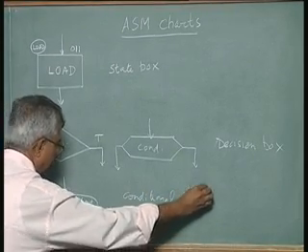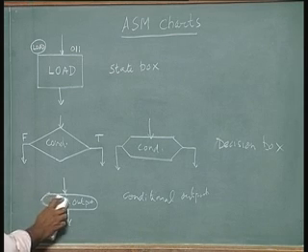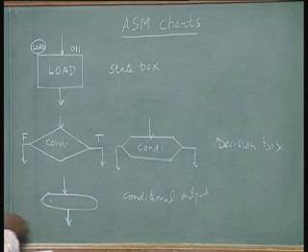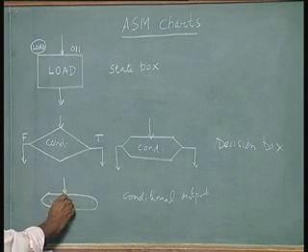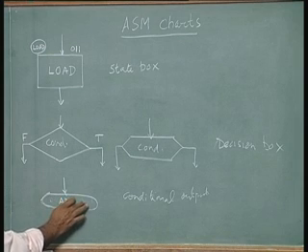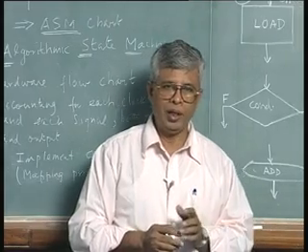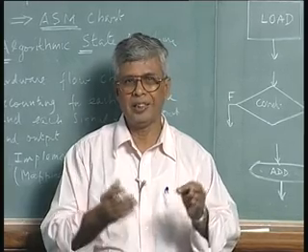As an example, it could be shift or add, let us say add. In an algorithm like a multiplication algorithm, the shift and add algorithm, you know that we do addition and shifting if the multiplier bit is a 1, and we only do shifting without adding if the multiplier bit is 0. It is an example of a multiplier.